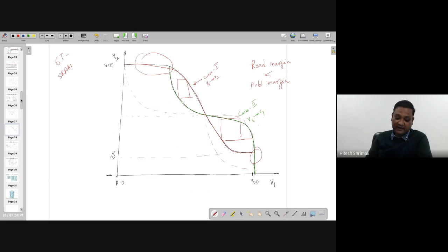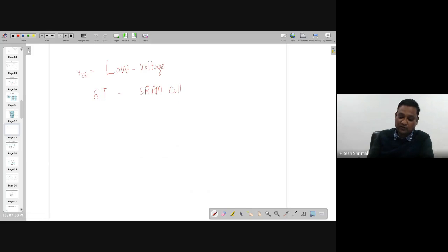Now, how to get this particular thing, right? I want to achieve this butterfly diagram. This is one thing, and this VDD is going to a very low value, maybe 0.9, 0.8 volt for a given technology node. So in that case, as you are going to low voltage, you might not get the output as you want, and sometimes it happens that you are not working in the required mode of operation, but it's working in sub-threshold. So your transistor might be conducting in sub-threshold, and in that case, you need to think about some dual port technology or the dual port method.